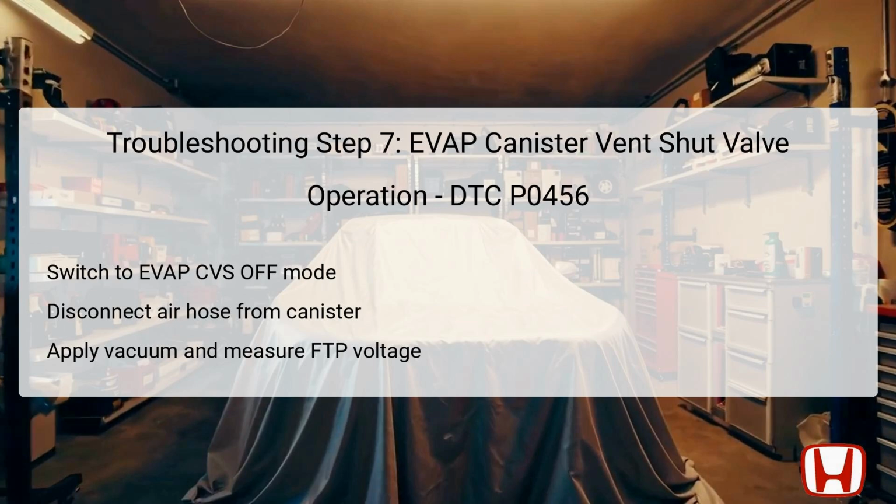These tests confirm whether the vent shut valve is allowing proper vapor flow control, which is critical for detecting leaks in this segment of the EVAP system.